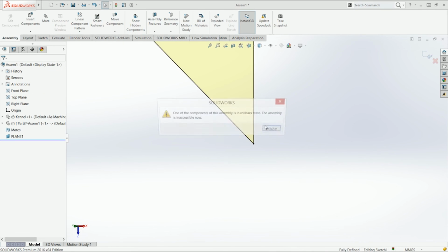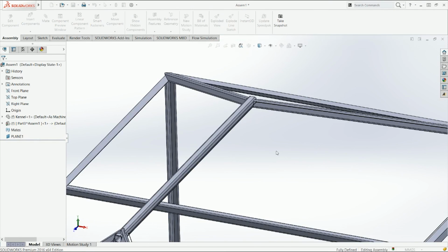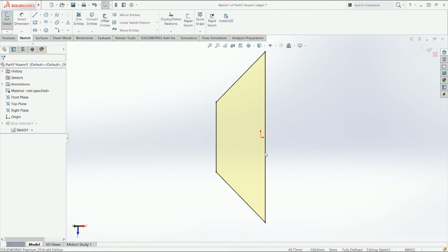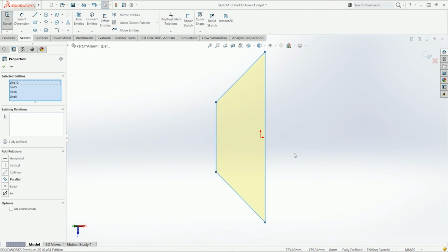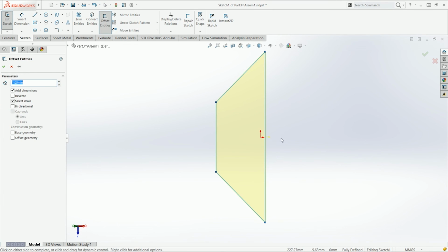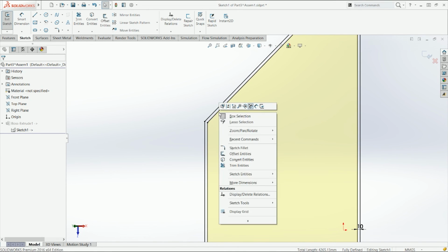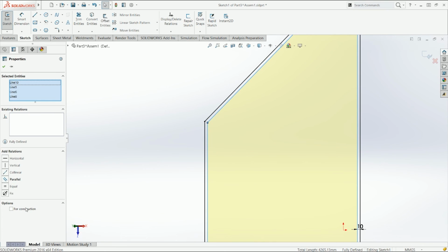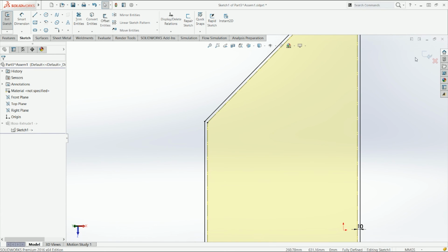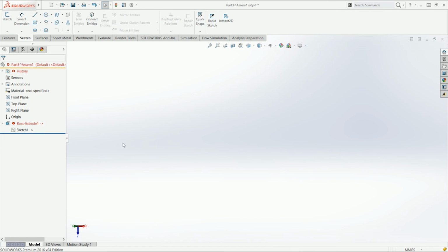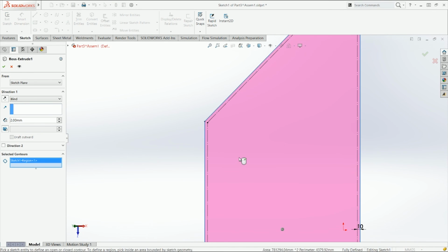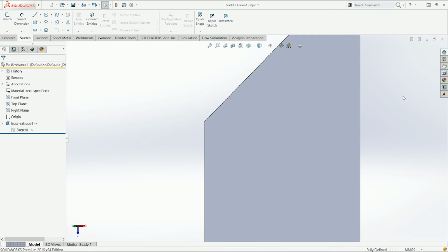And since I want it a little bit bigger, because I just chose the insides, I'm going to right click, select chain, and then just go offset. Let's say I want a 10 mil offset. We can play with that later. Right click on the inner line, select chain, and make it for construction. So now if I go out of here, it's going to give me a warning saying that the first region wasn't there, so I'm going to click on the second region, and we don't have any issues anymore.